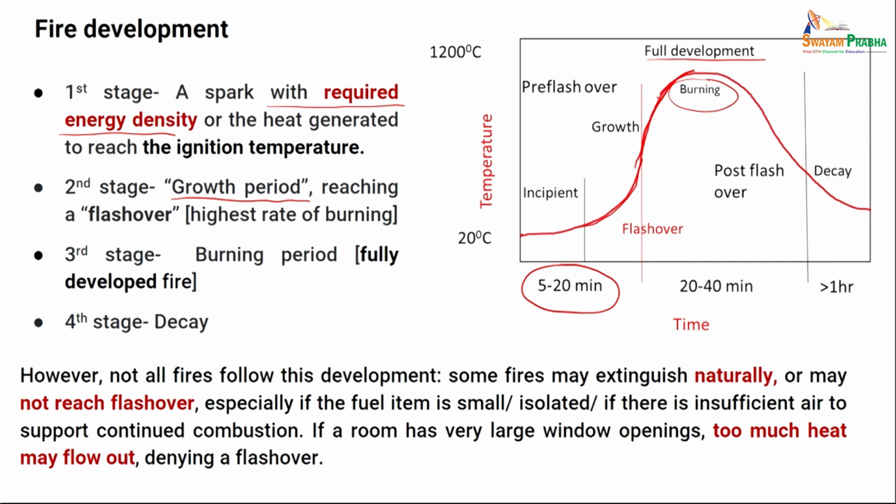You see here an S kind of curve forming in a very short period of time, and the burning continues for another 20 to 40 minutes depending on the fuel size, obviously. During this full growth period a lot of things can happen. This flashover period is very important, and by this stage the people need to be taken out of the building. That is the principle. We will go into that in detail later on.